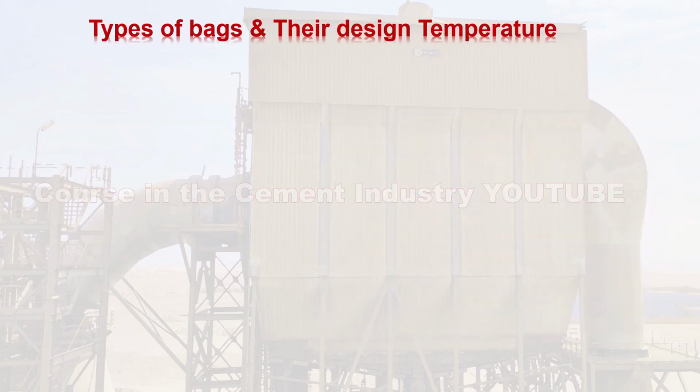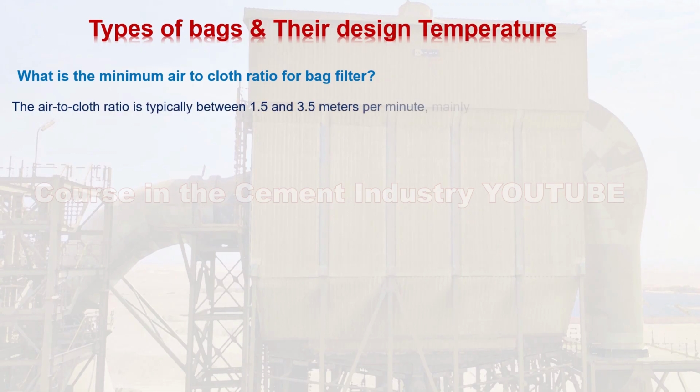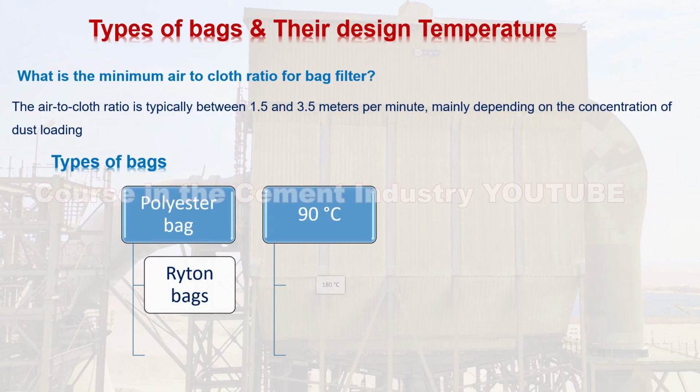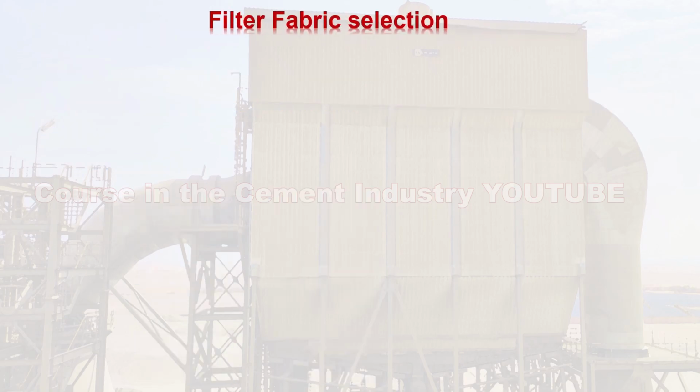Types of bags and their design temperature. What is the minimum air-to-cloth ratio for bag filter? The air-to-cloth ratio is typically between 1.5 and 3.5 meters per minute, mainly depending on the concentration of dust loading. Types of bags. Polyester bag, 90 degrees Celsius. Ryton bags, 180 degrees Celsius. Mixed felt bag, 350 degrees Celsius. Filter fabric selection.